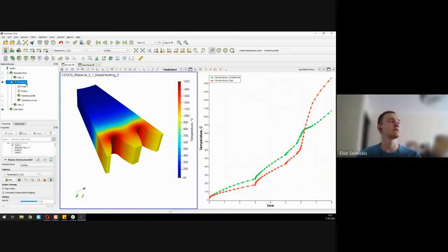Then to do that, we click on the workpiece here, and right here a little bit higher, we have the option to clip the workpiece. So this will actually cut it open, but it will leave the volume still there, but it will be cut. And then the other option is to have the slice over here. So this will make a 2D slice of our workpiece's 3D volume.